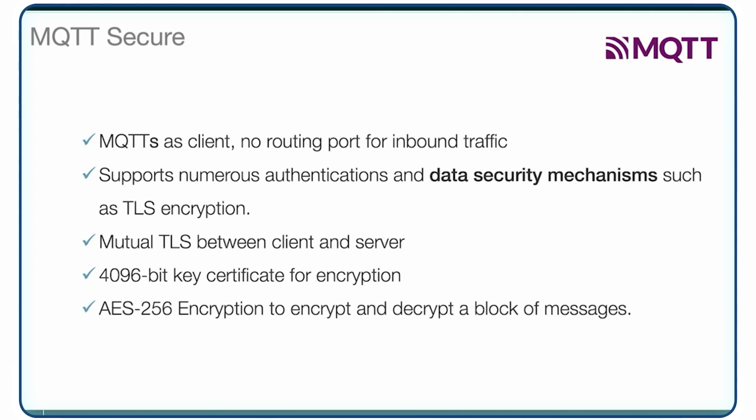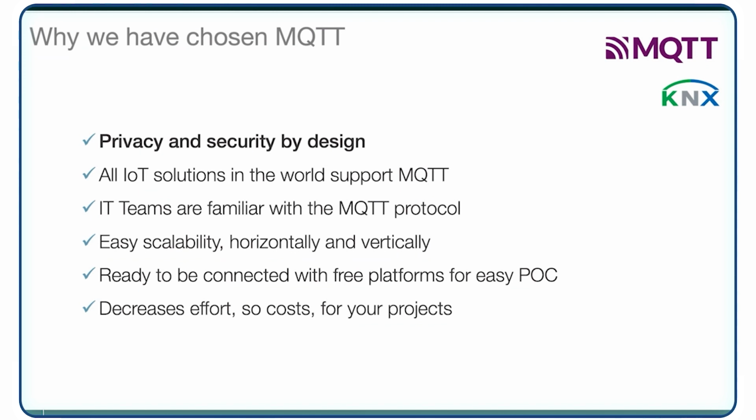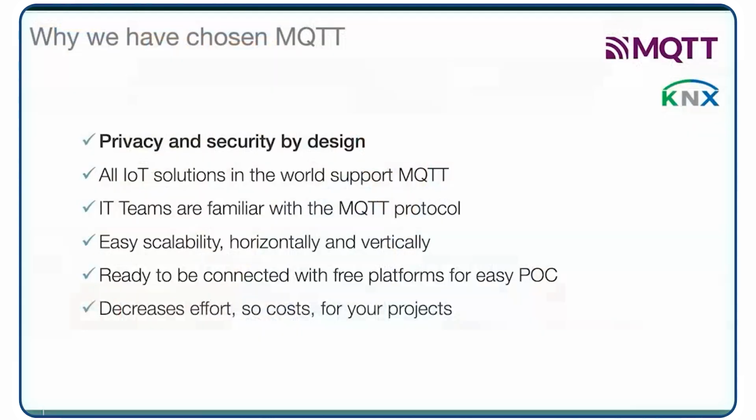AES-256 cipher technology. Why have we chosen MQTTs? Because privacy and security is by design. Many IoT devices are based on this protocol, and IT teams are familiar with this protocol, so easy to install, easy to use. MQTT is also ready to be connected to platforms for big data collection and big data analysis. So now we have all the tools to design and to install a secure solution based on KNX. And we are also able to connect big data.